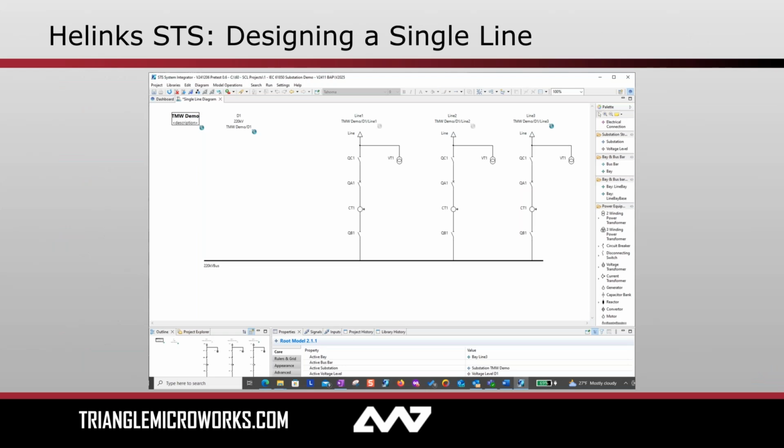Now in lieu of a demo, I just have a couple quick screenshots to walk us through the engineering process using the tool Helix STS. Beginning with the specification stage, we start out by designing our single line diagram, which is what we see here. We pick the different pieces of conducting equipment and choose how they're going to be connected.